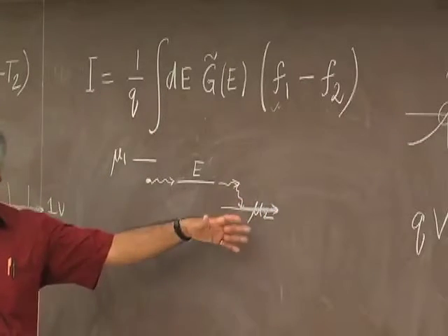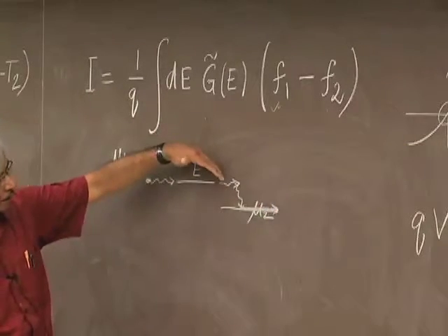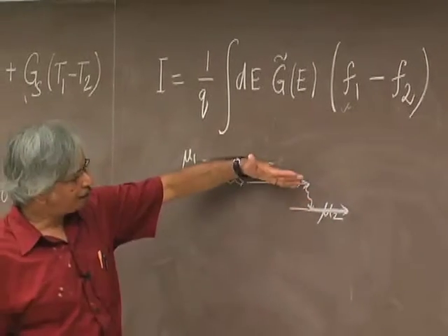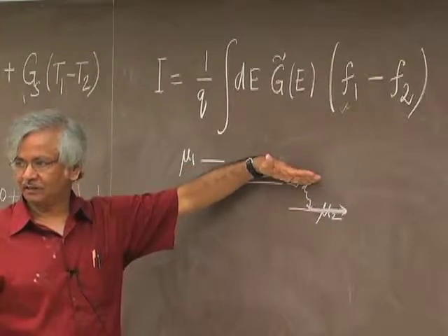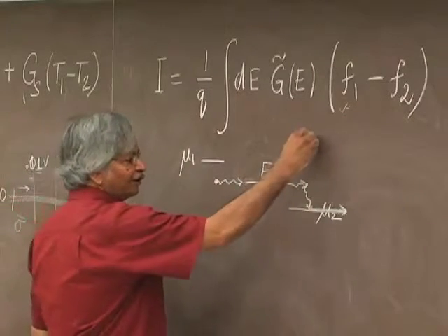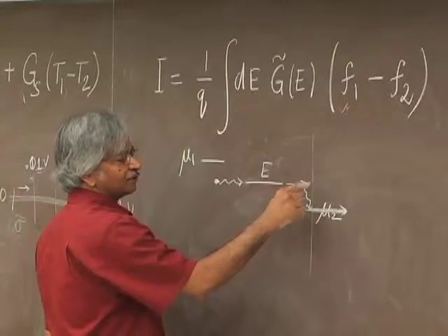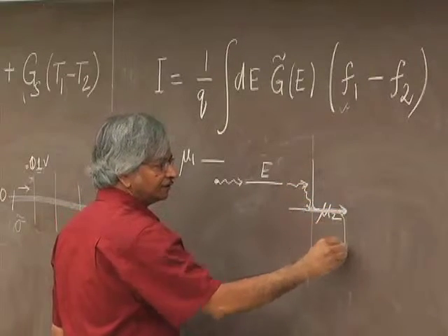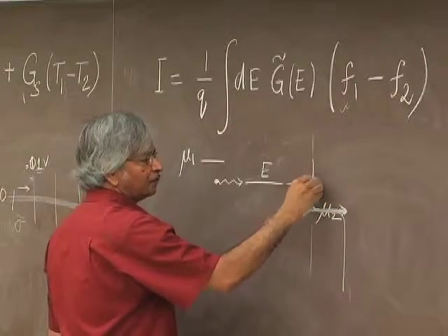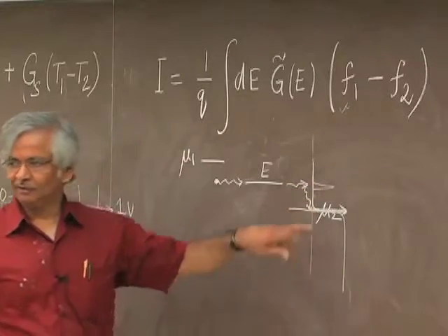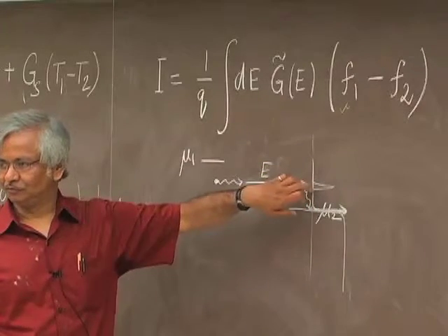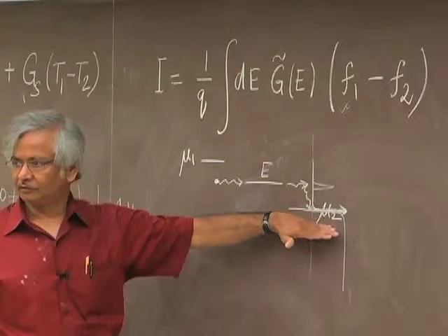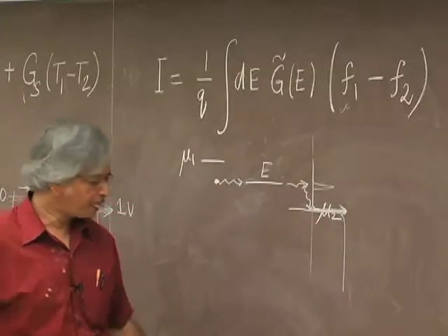According to this del F del E function, once it has come back to equilibrium the way it wants to, it won't have all these hot electrons up here, because when you look at the occupation, once the electron comes out here, this contact really likes to have a Fermi function, and an electron up here looks like an anomaly. I mean, it looks like a big spike at an energy that shouldn't be there. And so all inelastic processes will quickly lower it down. That's what it does.